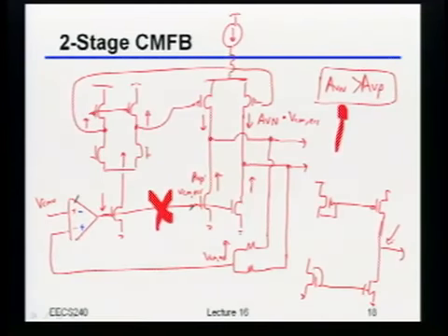You may think you do, but trust me, you don't. Because if the output impedance is high, there's no feedback, there's no nothing that's forcing it to be there. I just have two current sources, and the two current sources, I tied them together, so the voltage, at least if they were really current sources, could be whatever it wants. Does that make sense?